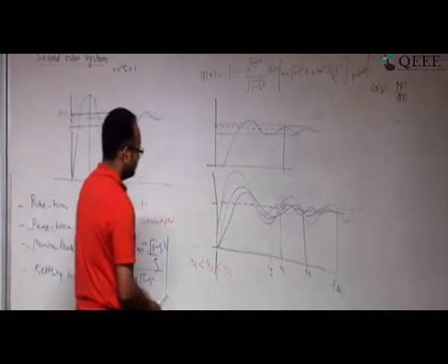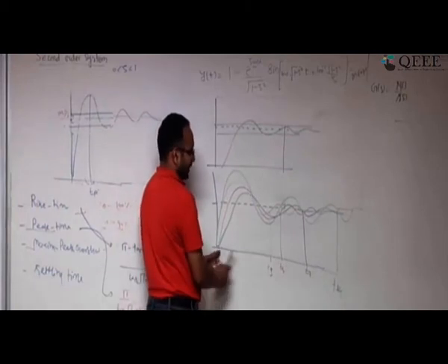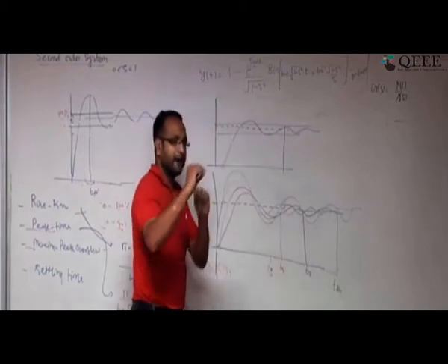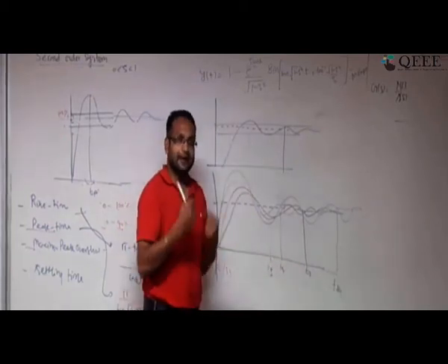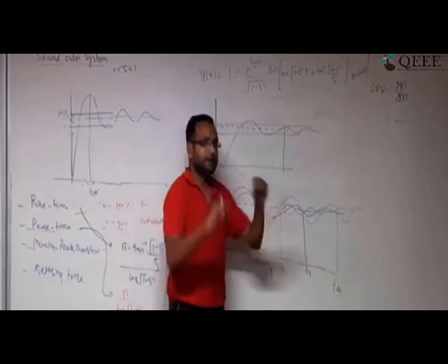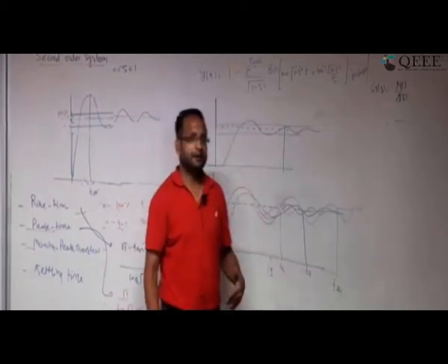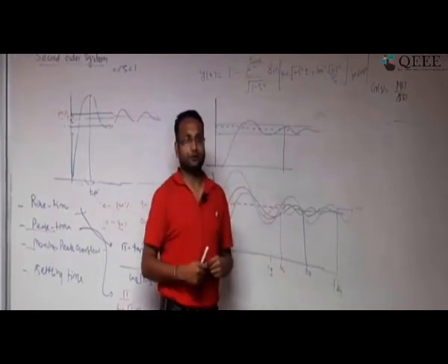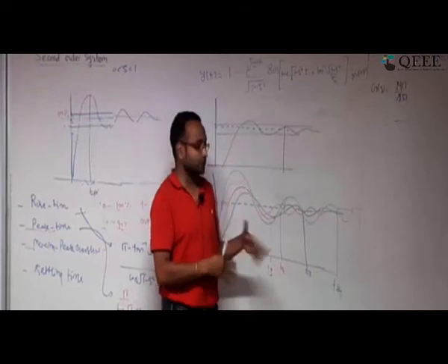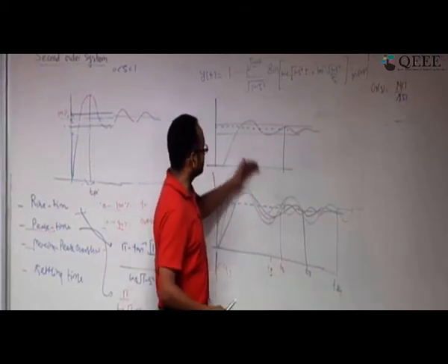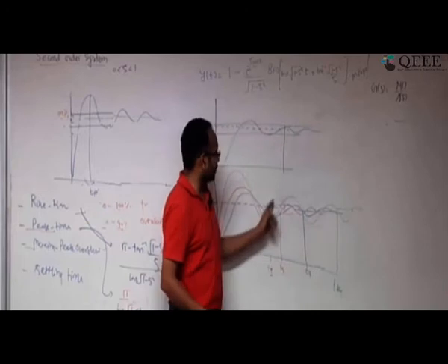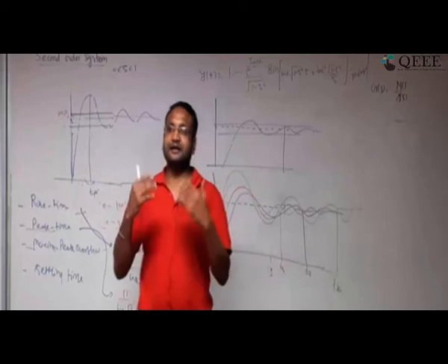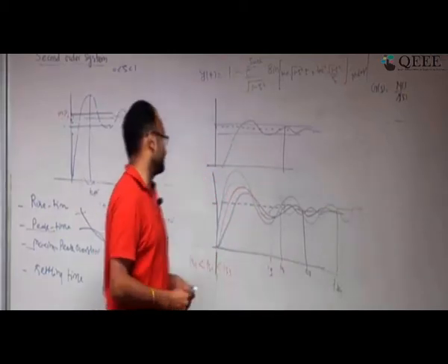So this part is clear. What I am saying is about the settling time. I used some zeta, analyzed it, and saw that it is reaching the band earlier. I reduced my zeta, the damping factor, further, and saw that it is reaching the band much earlier. Then I reduced it much further, and the settling time is further reduced. But if I reduce to the next level also, then what I observed is that, because of this oscillation behavior, I will be coming out from the tolerance band and I will be reaching my tolerance band very late. So my settling time has increased, which is not desirable.